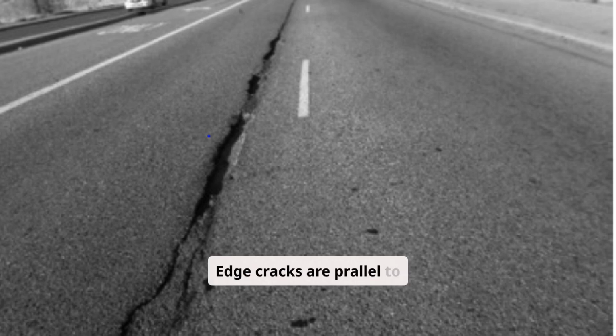Edge cracks are parallel to the roadway and occur within 1 to 2 feet, 300–600 mm, of the outer edge of the asphalt pavement with no or partially paved shoulders. This cracking is initially caused by lack of lateral support from the shoulder or base weakening due to poor drainage and/or frost action.